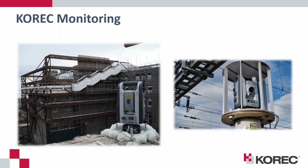As you can see there from the pictures, we set up high spec monitoring total stations with prisms or other devices located around your project, and the software is driven so it will take a measurement every so often and feed that information directly to yourself or back to the project management team, and alert you if there's something dangerous going on with nearby construction. So that's something that we can always bring into your project cycle if need be.